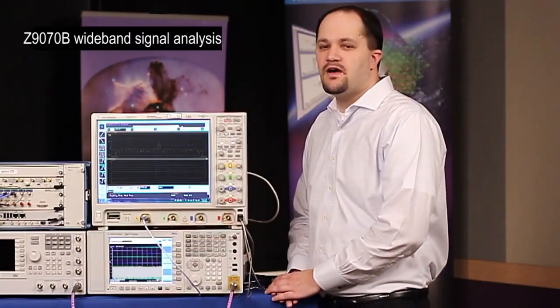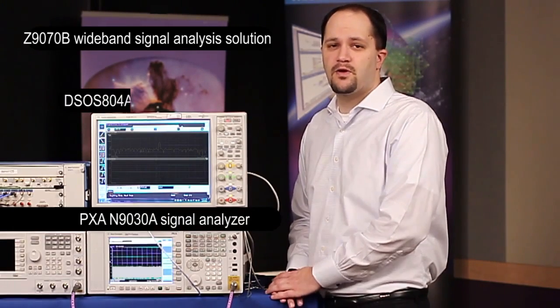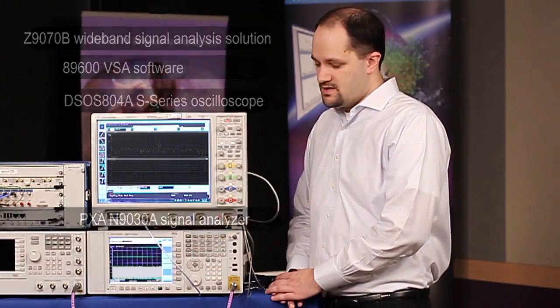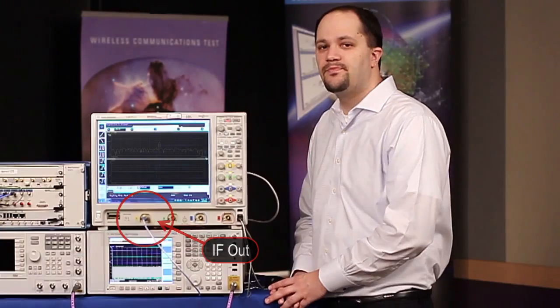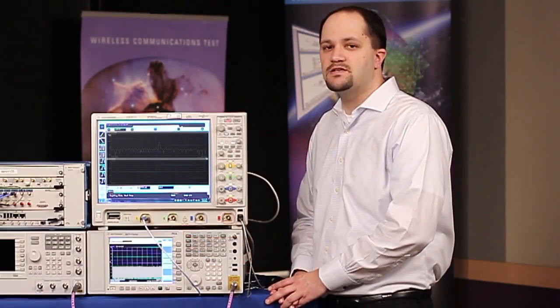So the setup consists of 3 things. The first is a PXA signal analyzer, the second is a high dynamic range oscilloscope, and finally the vector signal analysis software. The PXA's IF output is connected to the channel 1 of the oscilloscope. In addition, there is a LAN cable connected between the oscilloscope and the PXA signal analyzer.